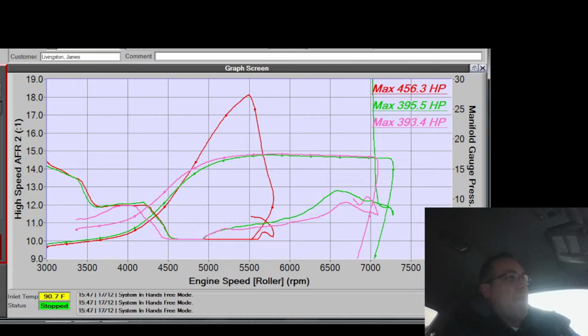So sure, if you're on a MAF-based system and you have a big front mount and all of that, the MAF will lag more than the map. But you don't get the option of changing that with the factory ECU. And unfortunately, if you're trying to cover that much sensor lag, that's rough, man, because that means you're really fudging it a lot. And that makes it just plain old difficult.